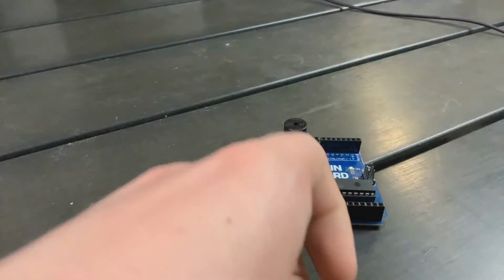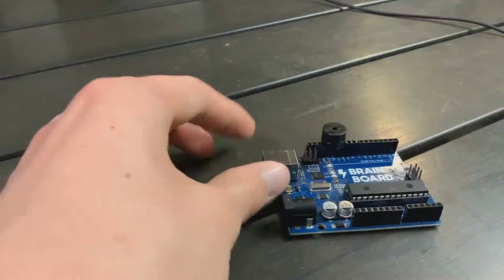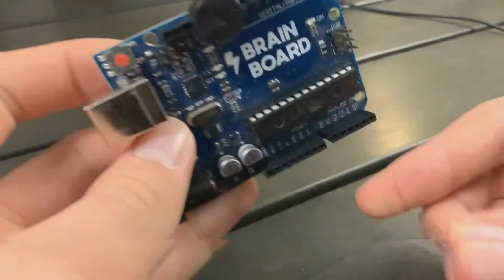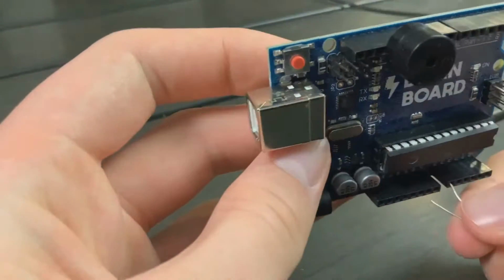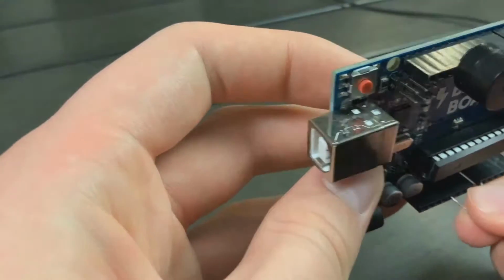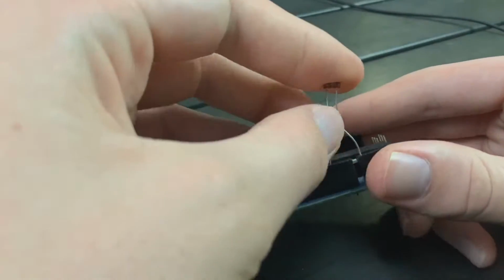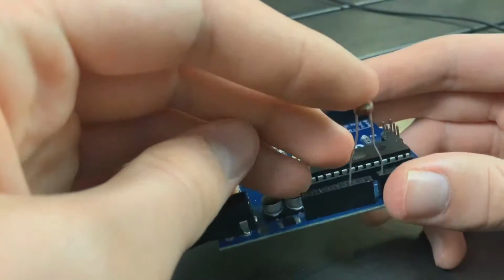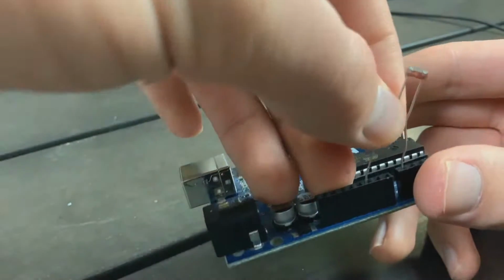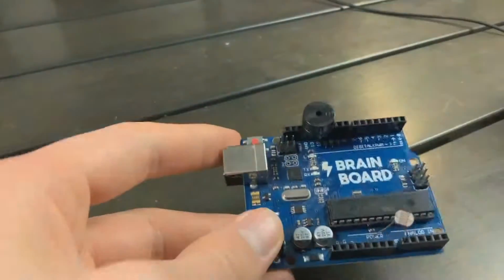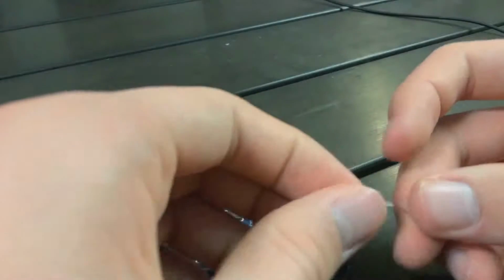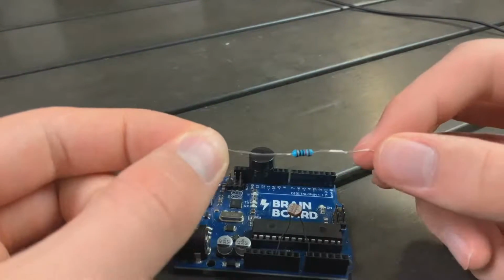Let's grab our light sensor. And like in the picture, you'll need to connect this to A0 and 5 volts. What you do is you line them up and then you push them in. Now it's important to make sure that even though these legs will bend a little bit, you don't want to have them touching. And it looks like I put this leg into the wrong hole. Perfect. Oh wait, no I didn't. It's meant to... Yes, it's meant to be in 5 volts.